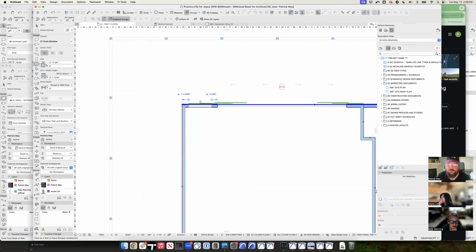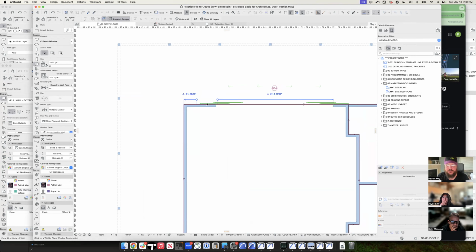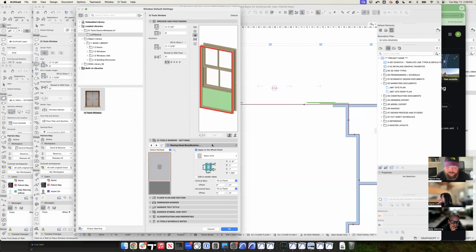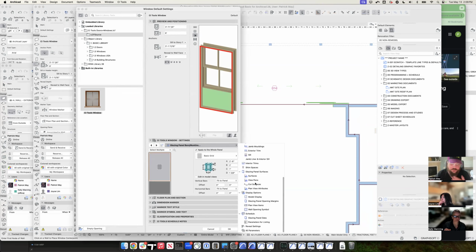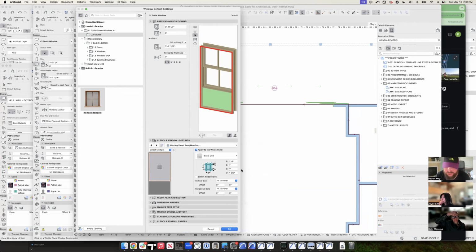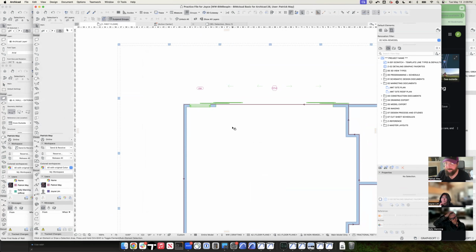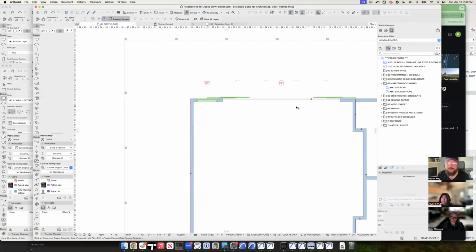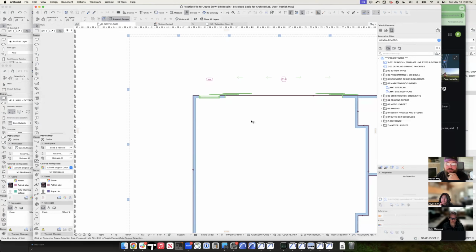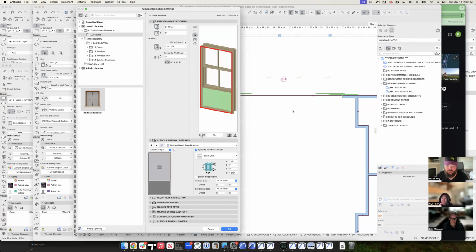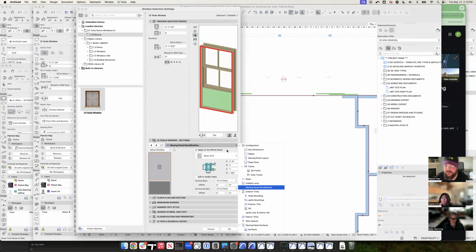And then placing a door or a window, I'm just going to hover over the wall. That little sun icon indicates which side is the exterior of the window versus the interior. That comes into play when we start talking about exterior trim, interior trim, connecting it to zones, and a few other things. But really, I'm just going to place here, and then decide which direction the swing would go if it was swinging. Okay, so that's the door and the window tool. There's a lot more to the windows. Like we can even adjust the head shape.